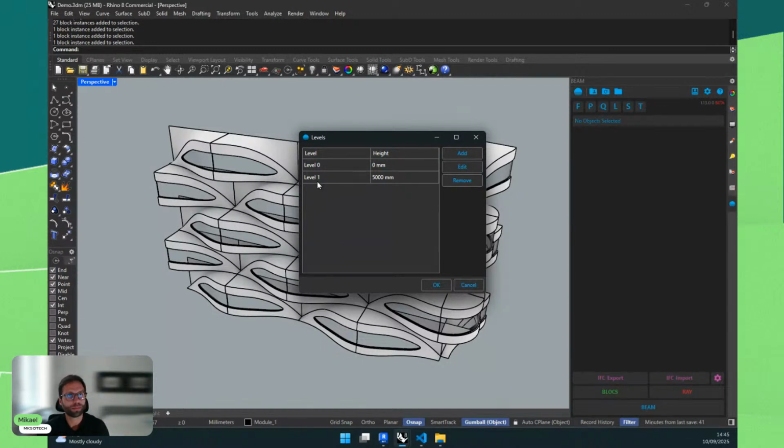So the thing is with BEAM, for IFC, we create the objects in IFC. For Revit, we first ask Revit if they have that object or if they have that element. So for example, if they have the material brass, we use the material brass from Revit. Otherwise, we create one. And then for parameters, if the parameter exists, we assign the value. If it doesn't, we don't assign the value.